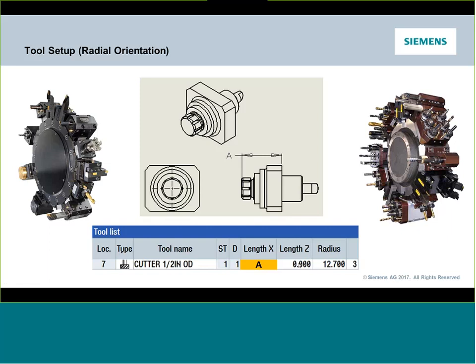Normally in a machine like this, we set these tools up one of two ways. Typically, they have a presetter, so you come down through the presetting routine, and the presetter will be datum relative to this reference point on the turret. I'd like you to understand why I'm getting these small positive offsets in my tool length. This is why, because everything's relative to these datums. Additionally, it makes it easy to preset your tools offline. I can go out to an external presetter, find that dimensional number, and just type it right in, so I don't have to go through the manual qualifying that I normally would do on a lathe.